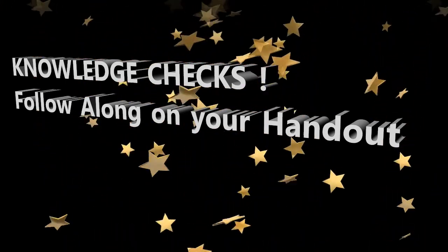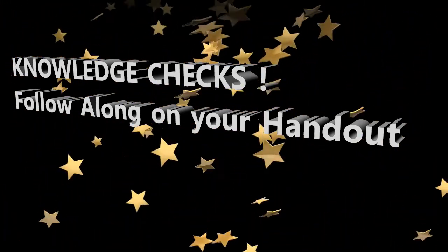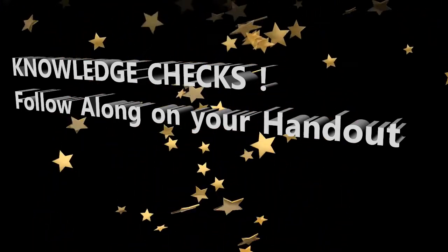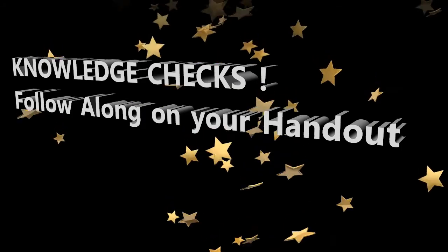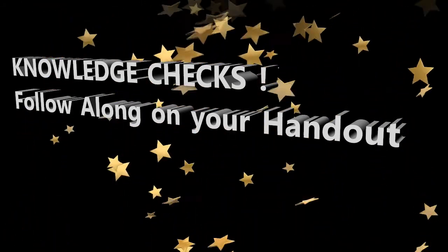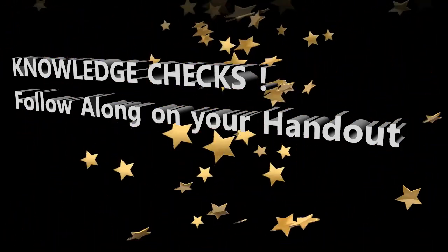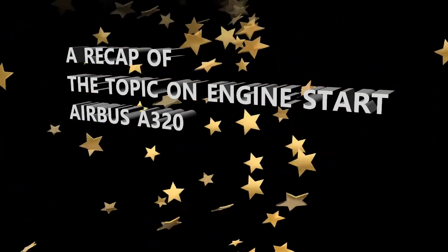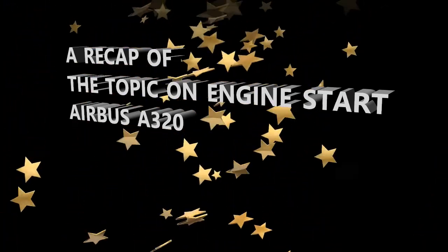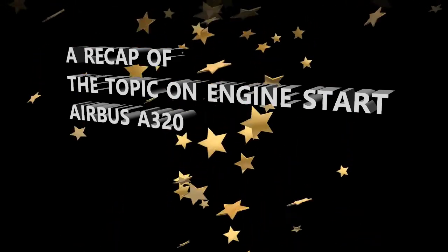All right. So I hope that gives you some familiarity with the engine starting. Just to recap, like I like to do, we covered the two biggest components. The start air valve, which can also be called the starter control valve, is basically the valve that allows air to flow to the starter.